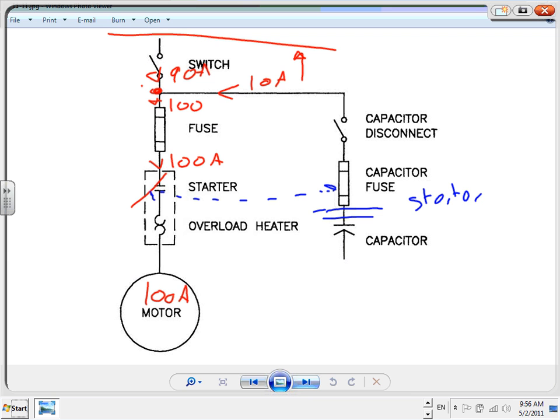And when you turn this motor off, at the same time, you turn the capacitor off. That's one way of controlling when the capacitor is going to come on. Guys, if you put the capacitor on and leave it on and the load that you need to correct is off, you end up with a leading power factor, high voltage, bad news. Just remember, you don't want to solve a problem to create another.